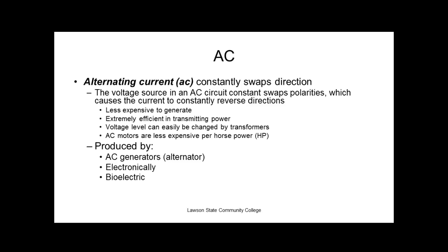But with the advent of solid state, eventually somebody figured out how to do it electronically. And this is when variable speed AC drives came up, and now they dominate. For a long time, that was DC motors' calling in life, when I needed speed control. Now it's going back over to AC. Why? Because AC motors are so much cheaper per horsepower.